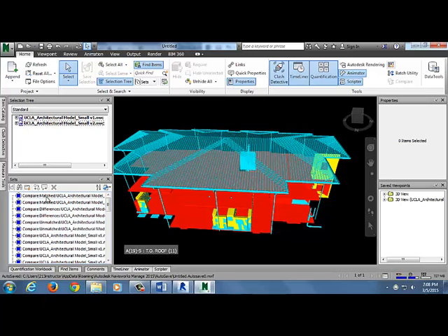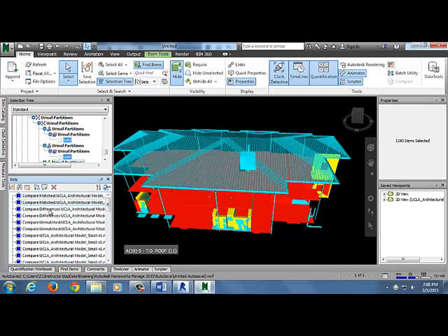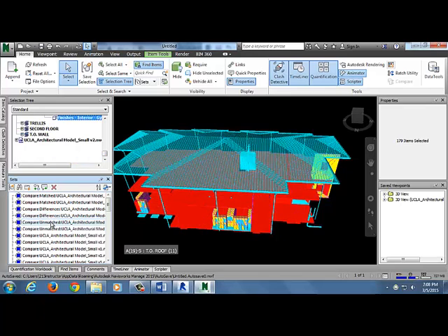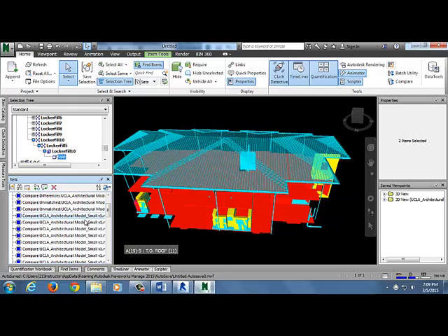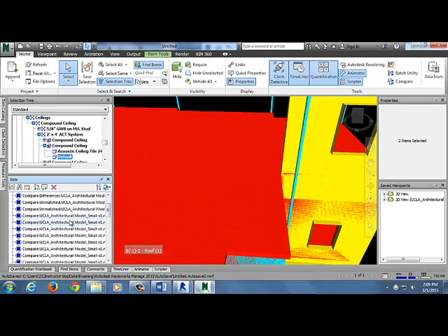So you still have the two matched, two differences, right, for each model, unmatched. And then if you go down here, it shows all the differences, each difference for each model item as its own selection set. So if I click on one of these and then hit page down, that zooms in to just that item that's selected.